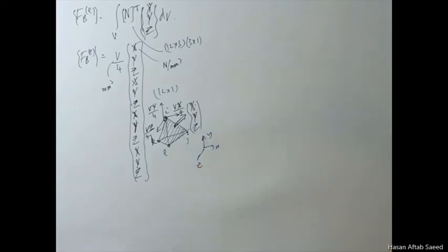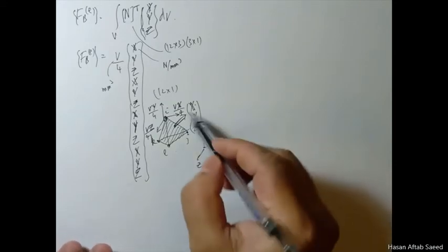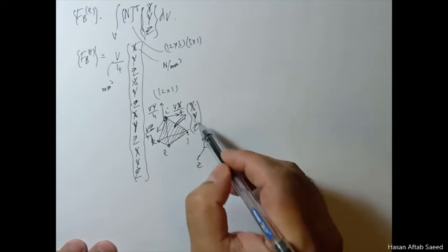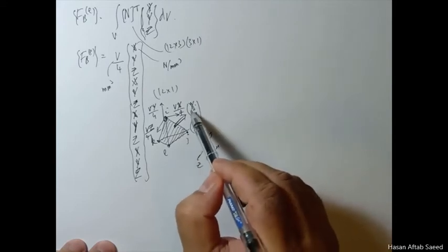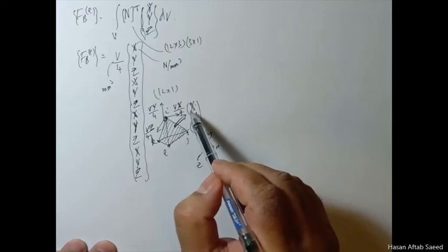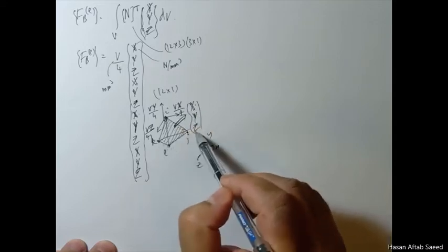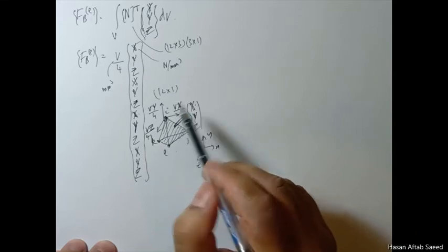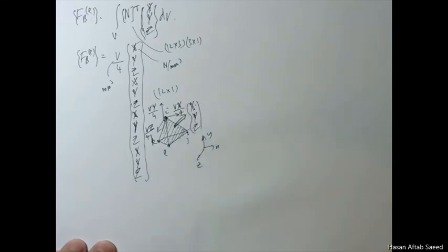It could have one component like in the case of weight, but it could be in any arbitrary direction. So for each component you multiply with the volume, get the force in newtons in that direction, divide by 4, and apply equally to all nodes. Same goes for the y and z directions. So it is exactly the same thing that we did in the case of 2D, and the dimensions, the size, and also the units just make sense.